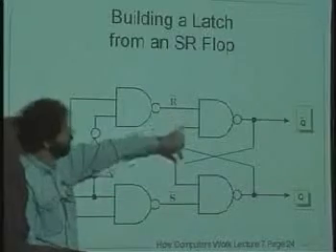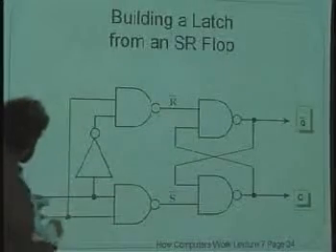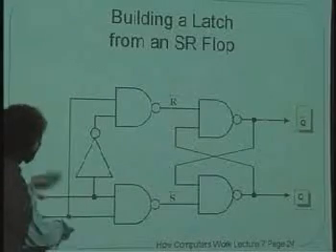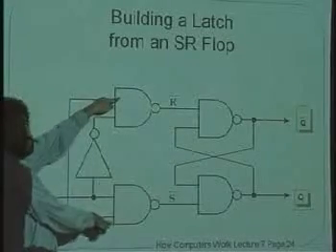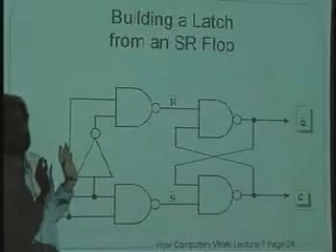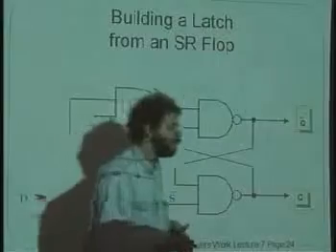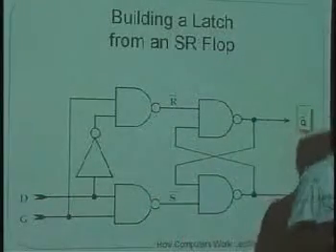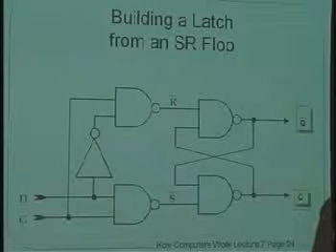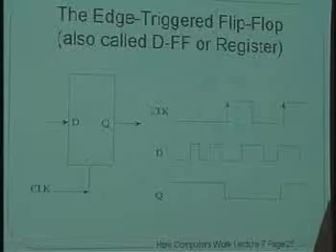And whether we teet or we tot depends on whether D is high or low when G is high. But if G is low, then both of these gates are shut off, and we neither set nor reset. And we leave the teeter-totter alone. So that's, again, just to show you, if you come across set-reset flip-flops, you'll think this is nothing new. This is the same stuff I learned about with the D latch.